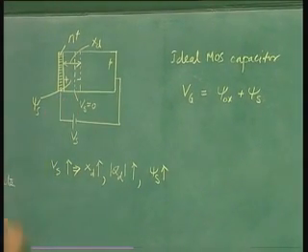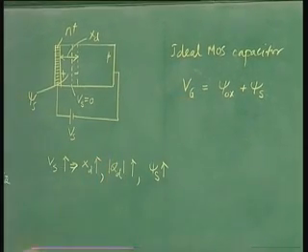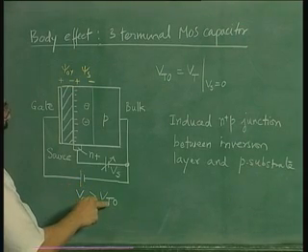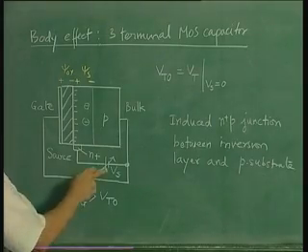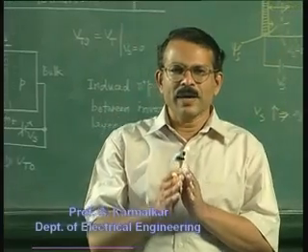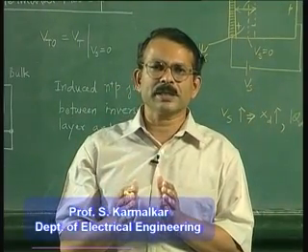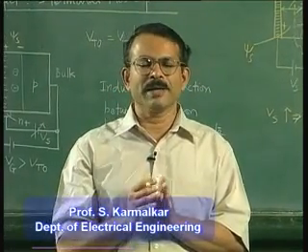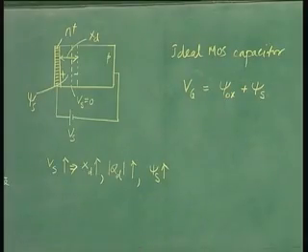Now if psi s increases but your gate voltage has been maintained constant, please recall this here. We have applied a gate voltage which is more than threshold voltage corresponding to 0 Vs, but we are not changing the Vg when we change Vs. That is how you discuss the effect of any input parameter. If you have a number of parameters in a given situation and you want to see the effect of any one parameter, other parameters should be maintained constant.